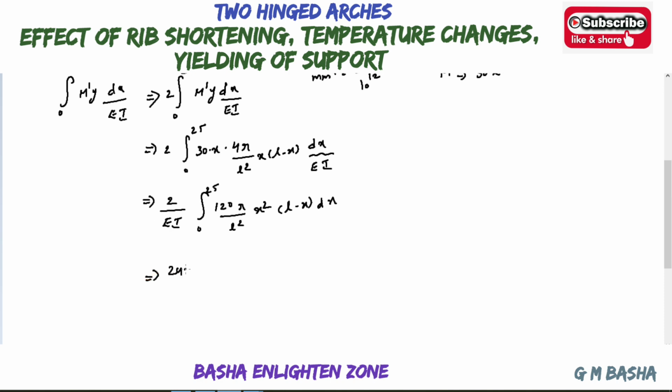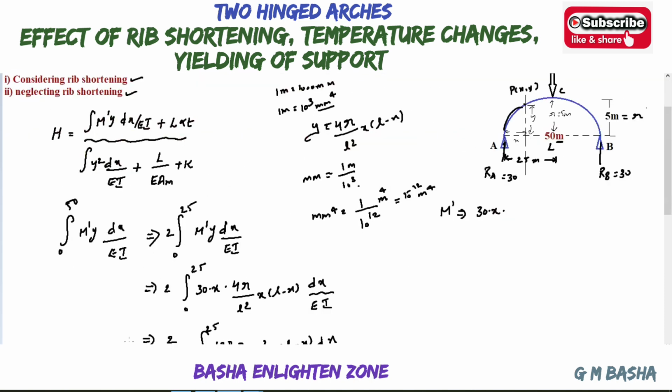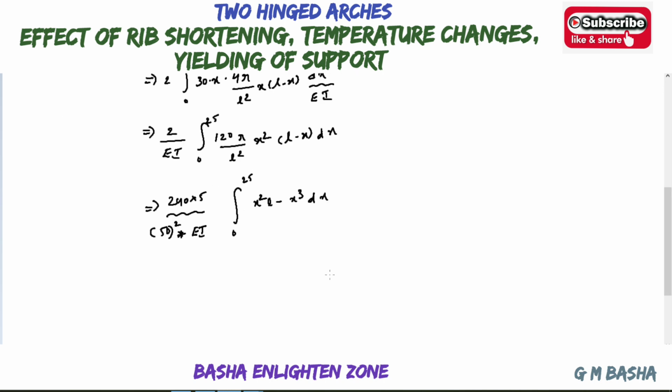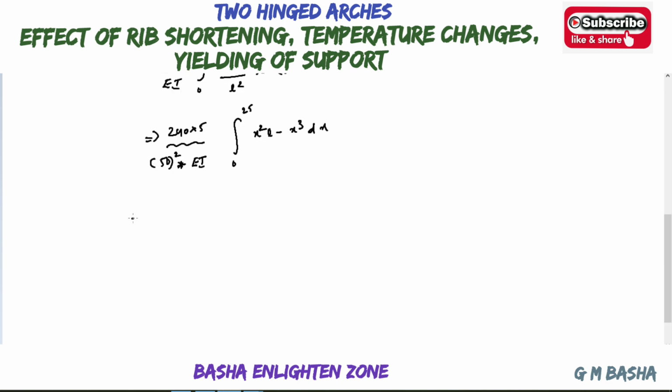240 r by L square EI. You have the value of r, and what is the value of r? The rise will be given in the question as 5 and the length will be given as 50. So 240 into 5 by L square, which will be 50 square, into the EI value. Take this down directly here and simplify that one also. Then the integral from 0 to 25 of x square into (L minus x) cube dx. And again simplify this one. How much will you get?